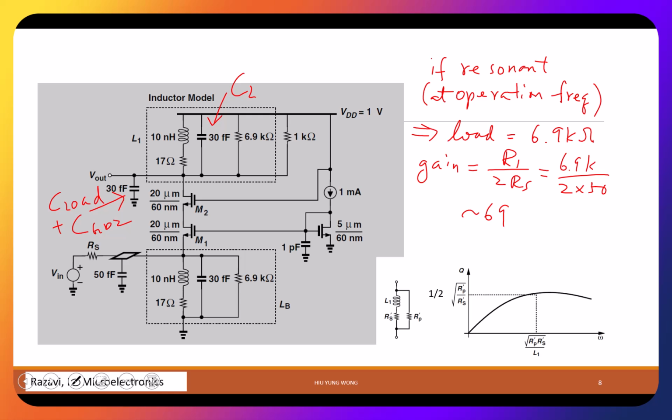You might think this is not a problem, but no. Distortion means that you have higher harmonics, because any curve can be approximated as harmonics: 5.5 gigahertz, then 11 gigahertz, and then you keep going up. And all this, when you go through the circuit, their gain has a larger slope when the power increases. Eventually, they will take over the base tone.